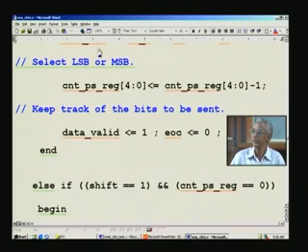Next time it comes over there, this condition will not be satisfied. A similar condition was there which was non-zero, and that condition will not be satisfied, therefore it will not reach this, and instead it will come to this and process from here. So, so long as shift is still asserted and the counter is 0, signifying that all the bits have already been sent, then we take this action.